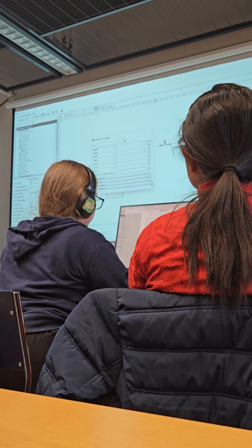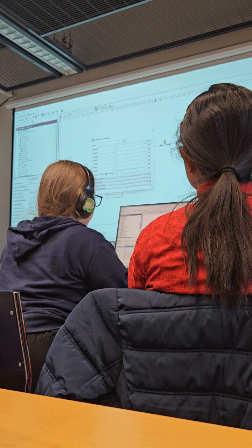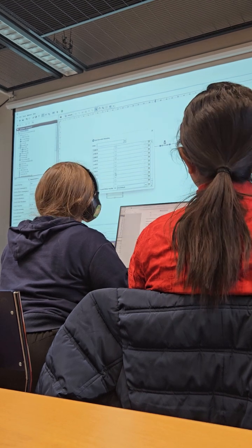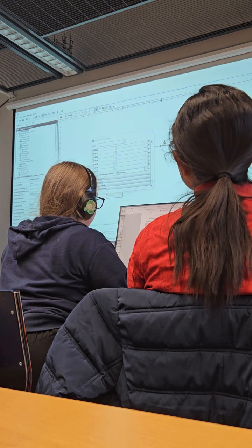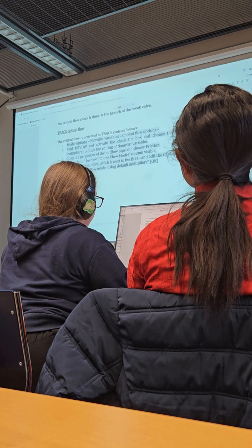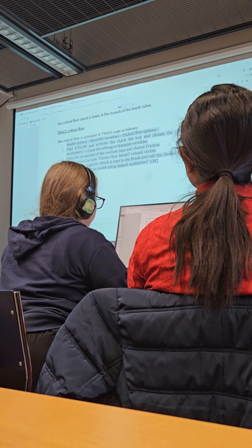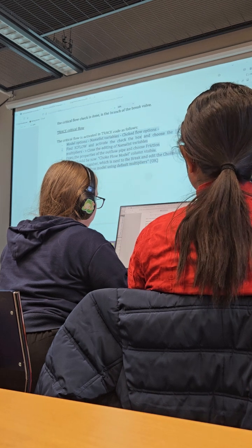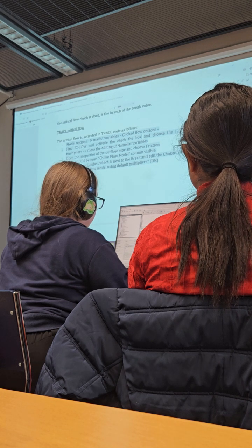And here is the last one, which is concerning the IC flow choke flow model. And then you can tick this box, and as it said in the instructions, choke flow model visible, and then use this number 1 choke flow model using default multipliers.